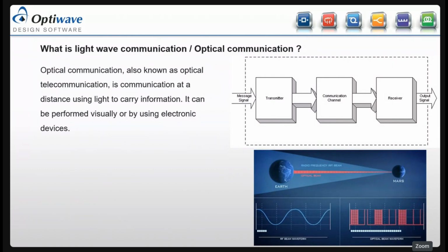In that case, there are further terms like eye height, intersymbol interference, bit error rate, and quality factor. These are some of the proper parameters which should be taken care of when you are establishing or maintaining a communication channel between two stations or multiple stations. First is bit error rate, second is quality factor, and third is eye height, or the eye diagram. It should have a proper eye height. These are some of the proper parameters.